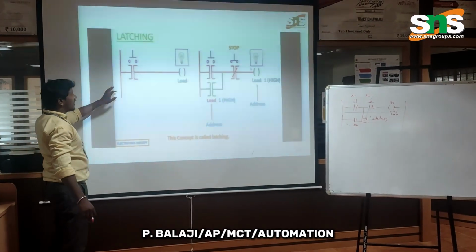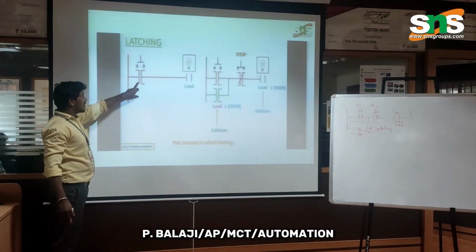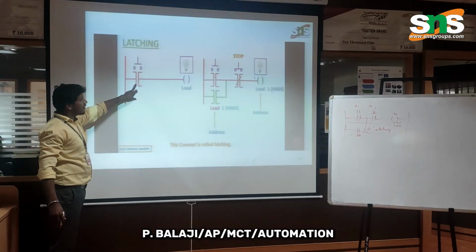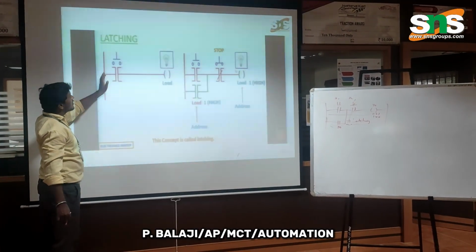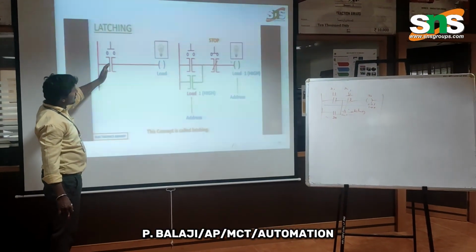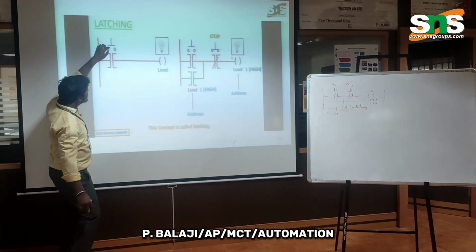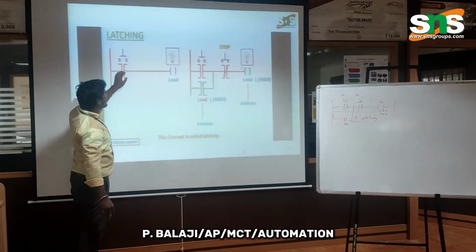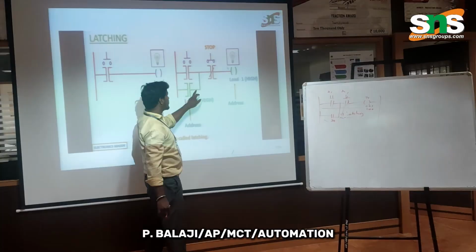It is an example of the latching circuit. It is an initial circuit. We have an input coil, normally open output coils, and the load is available. Suppose power is given, this coil turns on, and the lamp gets on. When you release the push button, the power goes off. So for this application, we add the latch circuit here.